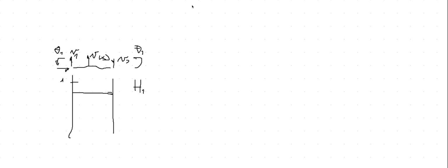So for 4 conditions here, you can build a cubic function h of x, and you say that your V of x would be equal to h1 of x times V1. Then, on the other side, you have a 1 value, then 0 slope and 0 value. So this will be your h2 of x.